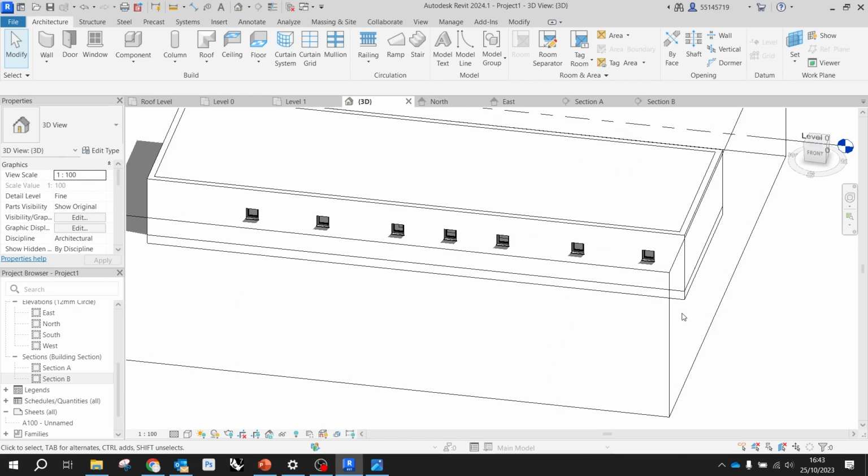You draw them on level 1. So basically what you would need to do, you either draw them on level 1 or you draw them unconnected if they are unconnected. I'll show you. So basically, when you draw the walls, you have to state their height. And it's easy to forget at the beginning when you start modeling in Revit. And you wouldn't think about it because you're drawing in 2D. But actually, you're drawing in 3D, right?